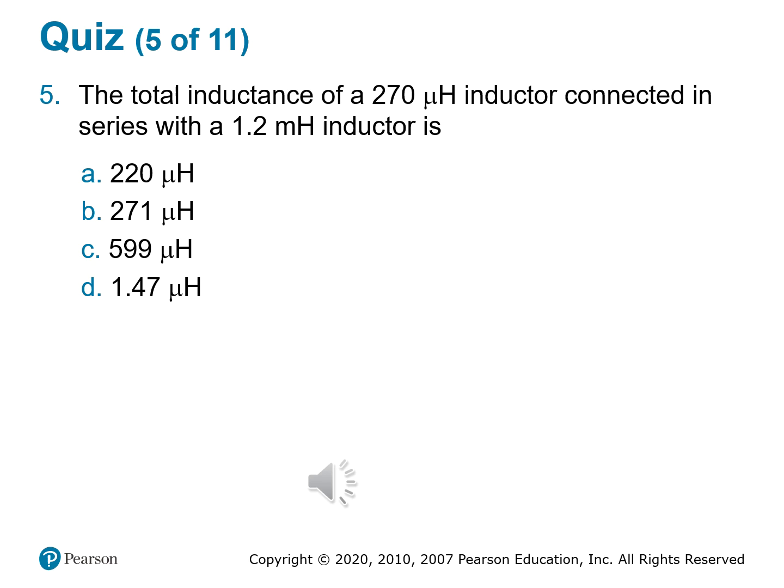So again, I've submitted this correction so many times. If you had a 1.2 millihenry inductor and you're adding another inductor in series, the answer has to be something greater than 1.2 millihenry. And none of the answers shown there are greater than 1.2 millihenry. So either D was intended to be the right answer and they put micro instead of milli, or something else. But I would guess that the right answer should have been D, 1.47, but instead of micro, it should be milli, the little m. I'll try to draw it and hopefully you can see it.